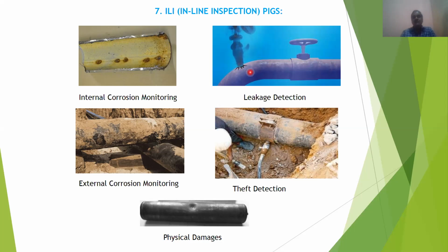And it is not only flow, it is also the type of fluid flowing inside the pipeline. That is also important. Maybe it is H2S conditions also. There are some chances to erode internally. Corrosion will take place, and from that area it will leak.